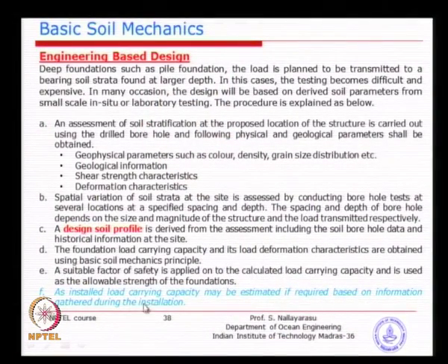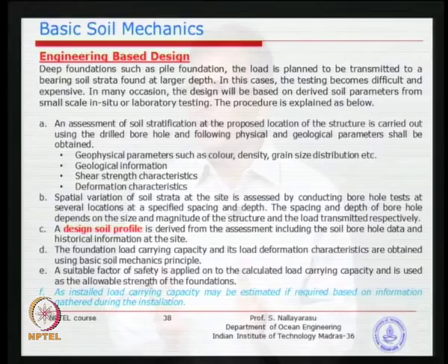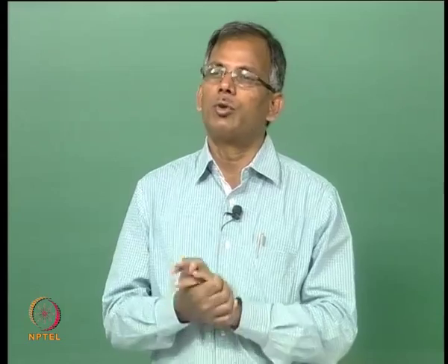So, basically, sometimes we do a back calculation during the driving of the pile. You can count the number of blows required to penetrate. For example, you take a nail, and if the nail is going through very easily, it indicates the soil is softer. If it goes very slowly per blow, for example, for 100 blows it goes by a very small distance, it means the soil is denser.